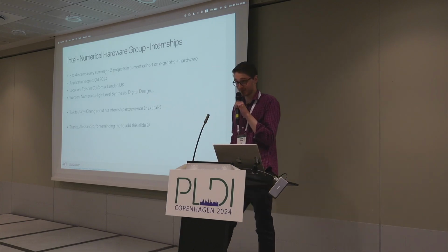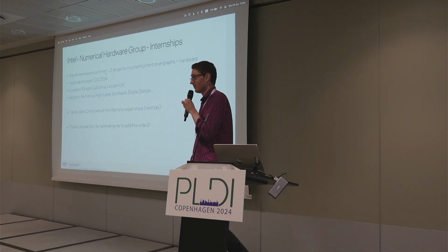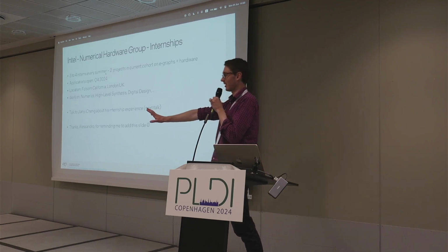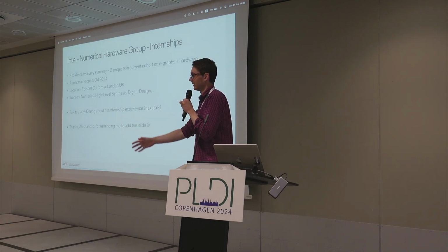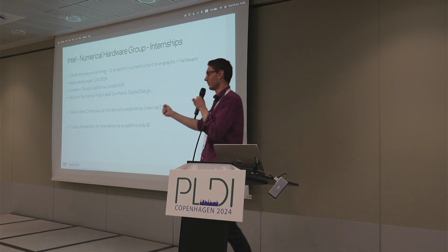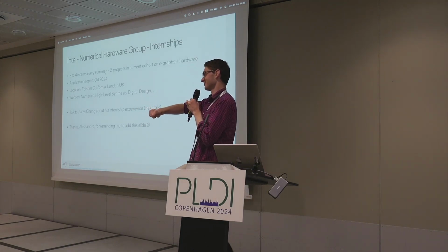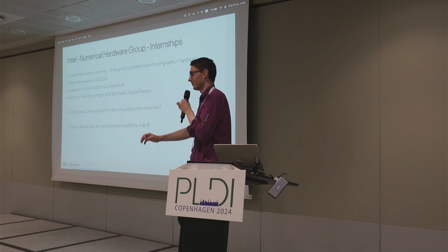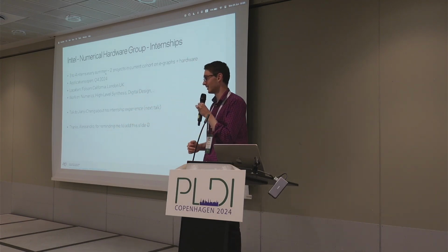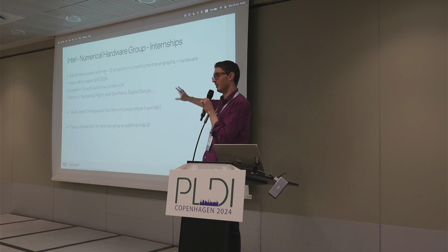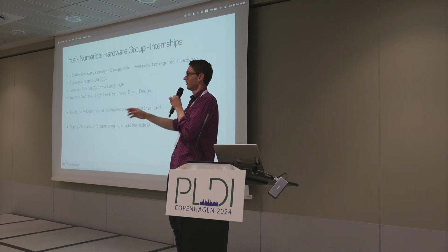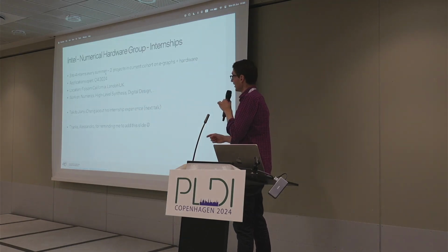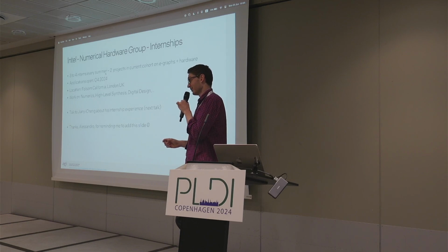So we try and take behavioral Verilog, in the sense that then you haven't guided it to these highly performance-optimized designs. That gives the tool a little bit more freedom to move things around. Whereas if you take really highly optimized Verilog, then you obviously have to undo certain things and then be able to apply certain transformations. You can still apply these techniques, but you'll probably look at more of a model of just adding operators rather than manipulating the structure if you've already pushed it to something highly optimized. On the first point, I have not really much experience with PDKs, so I can't comment, sorry, but we can chat perhaps.